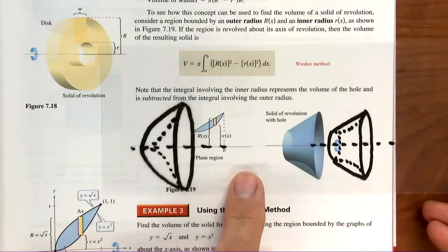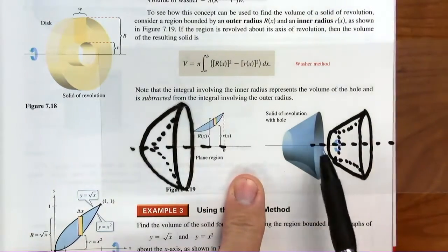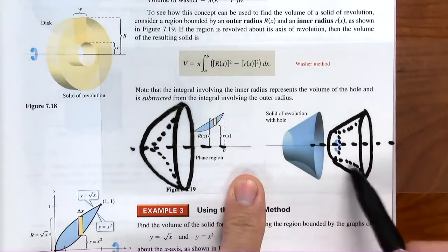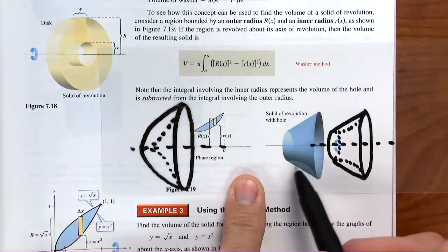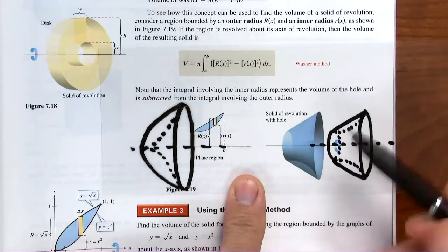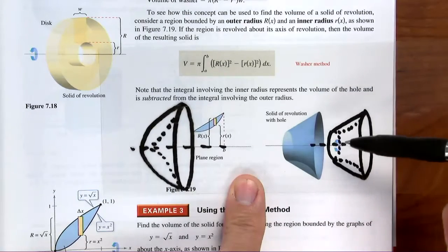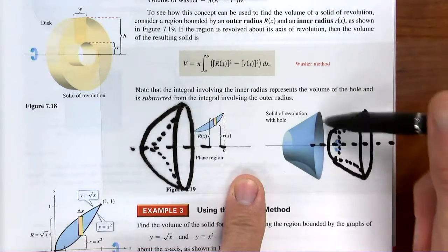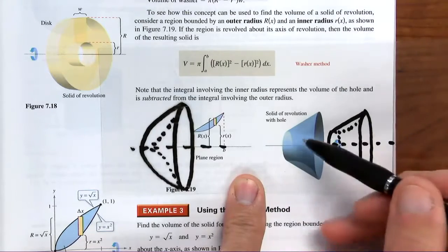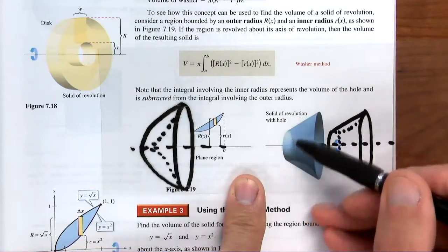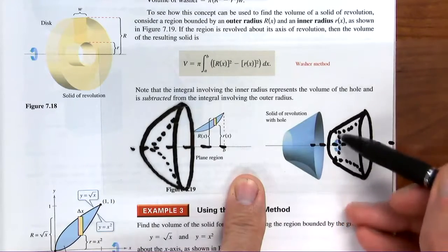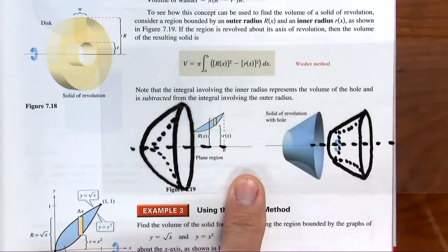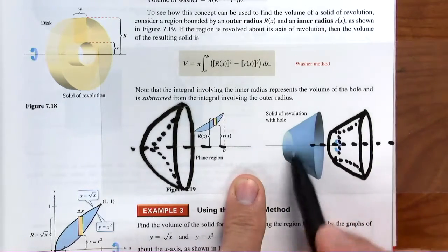You can see then that my dashed line right here is the axis of revolution. These other dashed lines inside of here are hidden lines. You can see this little curve right here. That's this curve right here. So when we look at this from that direction, that's the oblique view. We're kind of looking down in that direction. That's why you can see this face right here. This little piece right here is missing. That's what we're trying to represent with this dashed line. I could literally take my pen and slide it all the way through here because it's hollow on the inside. So this is what the nice picture looks like with all the shading.